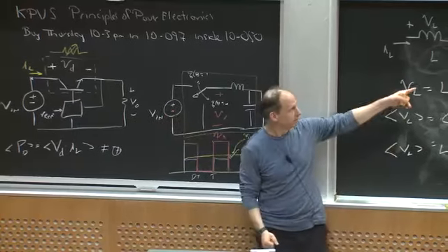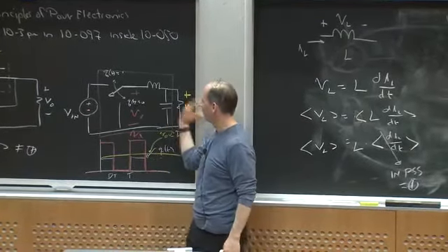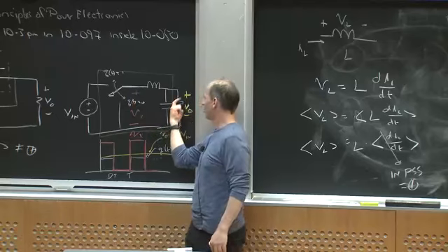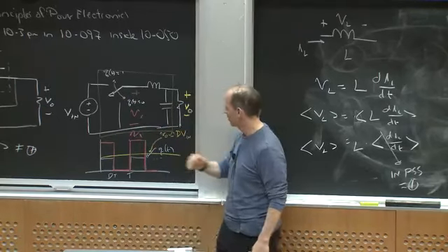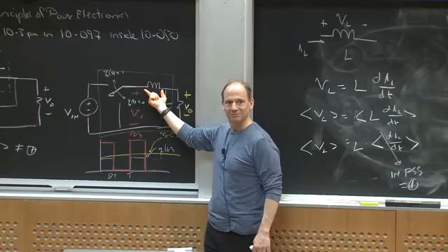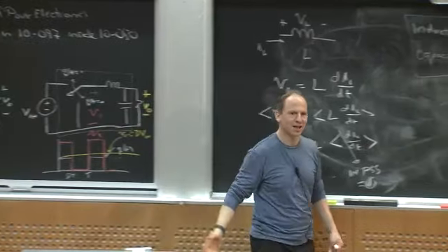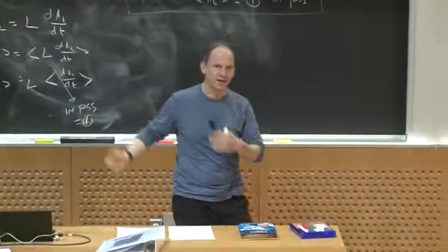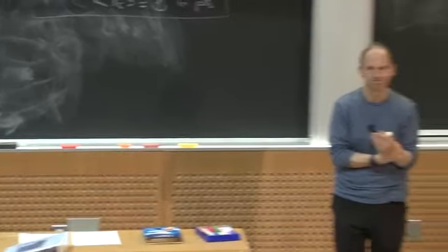And in fact, I did that subtly when I analyzed the circuit, right? We said this is a low-pass filter, right? The output voltage extracts the DC component of Ex. That's precisely the same thing as saying the average voltage across this inductor is 0, right? So we actually already used that subtly, but we just recognized that that was a low-pass filter. But it applies to any element in your circuit, okay?